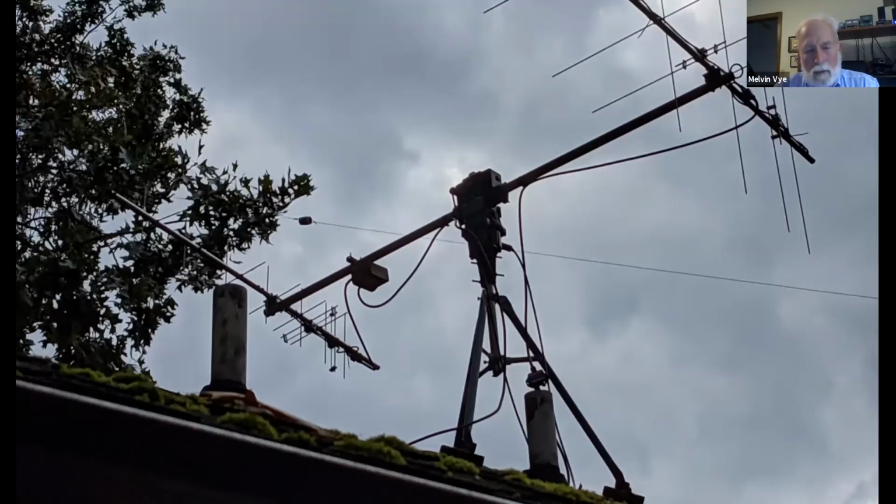So when we start, we look up on my roof, and you see here my satellite antennas, and you can notice that there are crossed elements on 70 centimeters and also on 2 meters. And the reason that they're crossed is that if you cross elements at 90 degrees in space and then phase them 90 degrees apart, and that phasing is done with a phasing harness, and you can see some of the coax right here, so that as the elements are 90 degrees in space and 90 degrees in phase, then the result is that you have a circularly polarized signal.